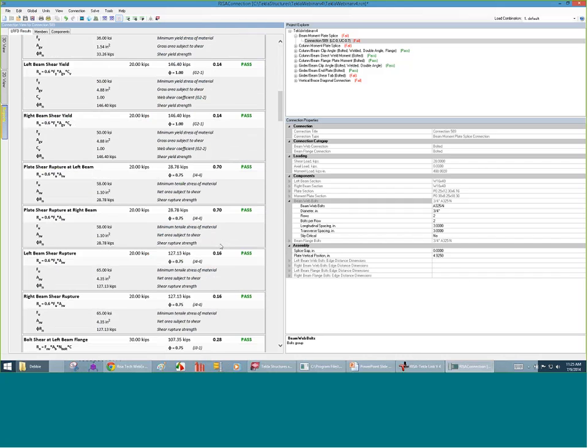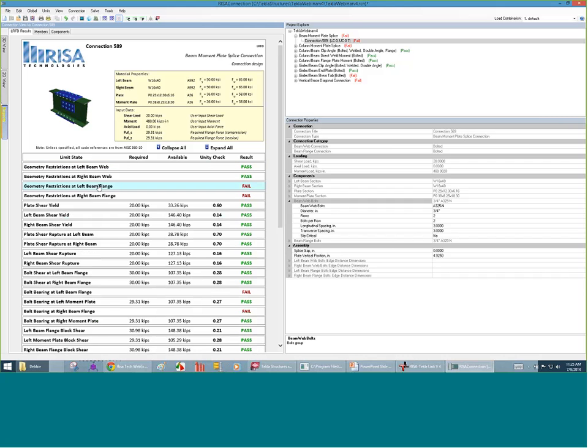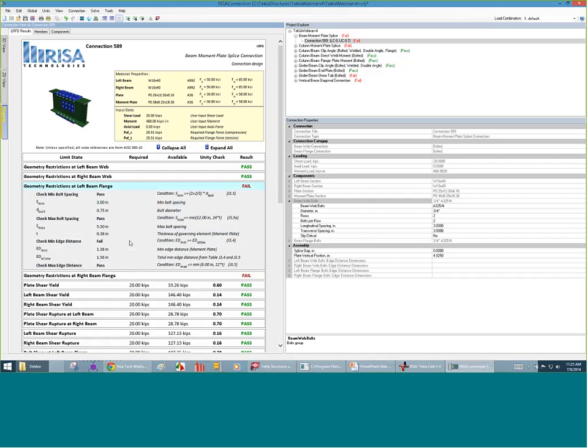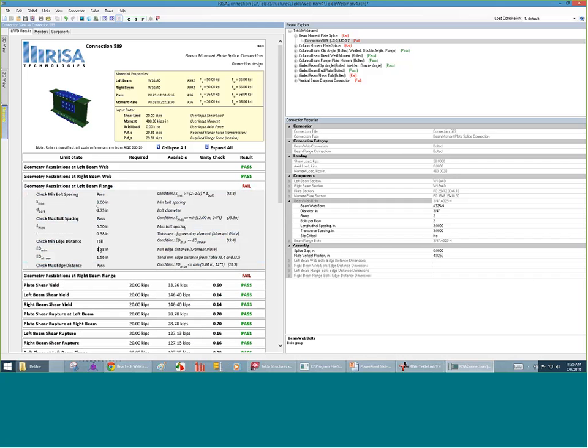That's a little overwhelming sometimes if you're just weeding through all the different calcs, so I always like to say, hey, collapse all, and as you click along, you'll see what's going on. Now, what you'll note is the ones that are failing don't have those numbers. So as we expand those, these are just pass and fail. And what it's telling us here is exactly what I thought. We're exceeding the minimum edge distance, so it's failing. So we're allowed to have 1.56 inches, and we are currently exceeding that. So we're going too small on that.